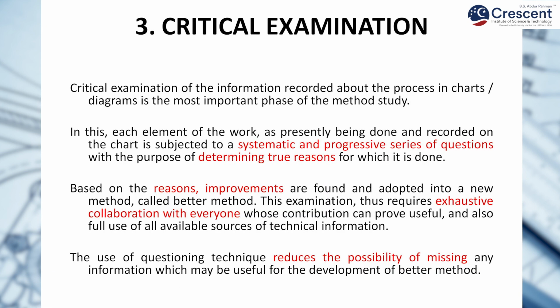Next step of method study is critical examination. We will analyze the information we recorded in process charts and diagrams critically, by a systematic series of questions, to find out the true reason behind performing the activity. If we know the true reason, we can better develop the method, and we will try to reduce the possibility of missing any information.